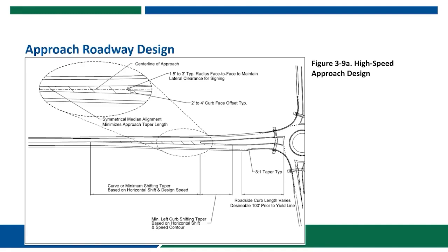A good visibility package can sometimes compensate for shorter length splitter islands. Curb and gutter also helps vehicles to maintain lane discipline and reduces speeds, and therefore introducing it in the transitional and low speed sections of the approach is encouraged.